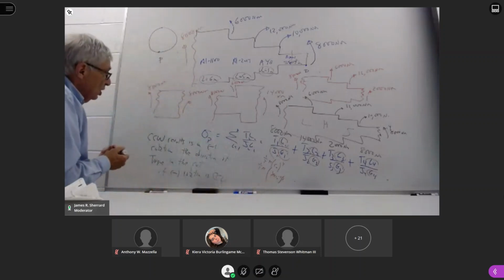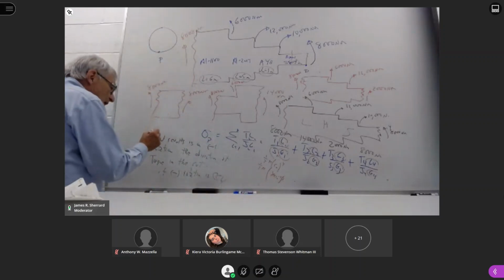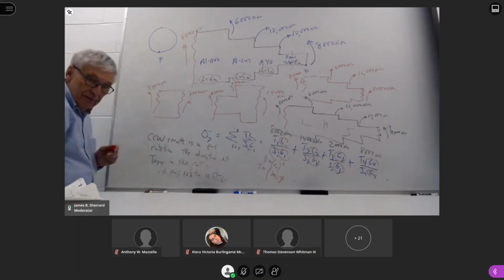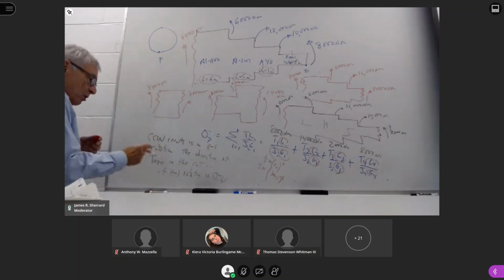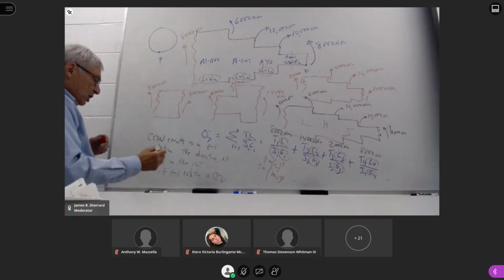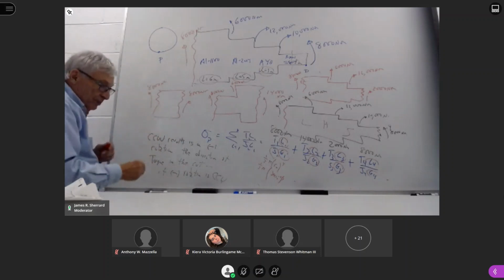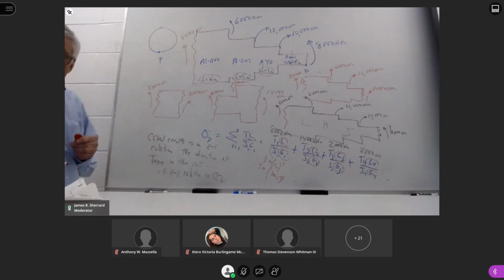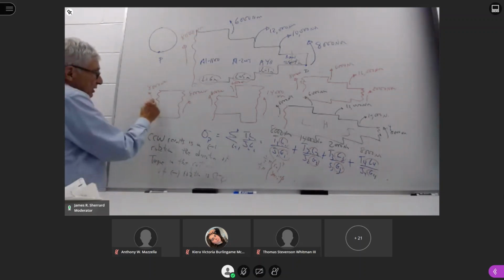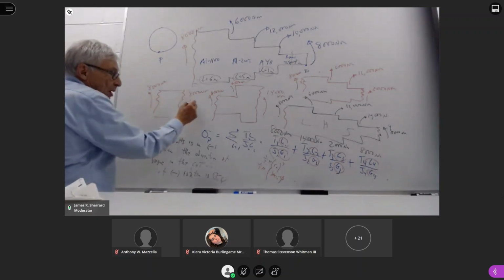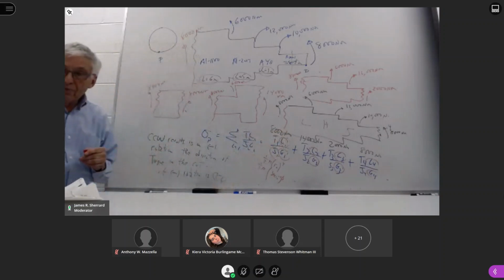Okay, let's go back and look at this. We have said counterclockwise means negative. Then we go back and look in the cut. If the cut has a counterclockwise torque in it, it results in a negative rotation. If we look at this first section, we came up with 8,000 Newton meters.